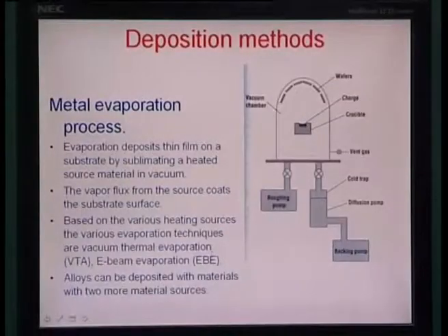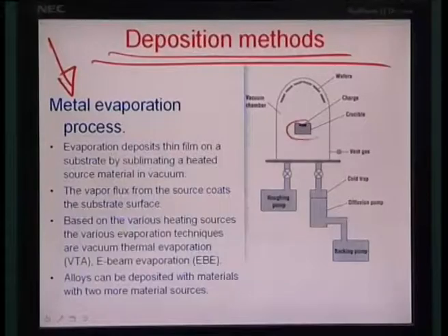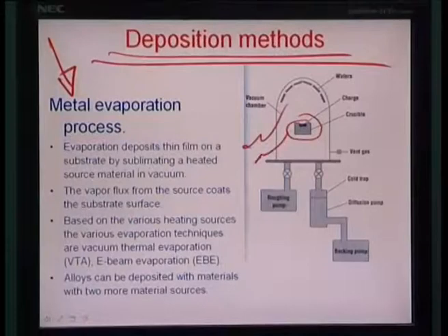Okay. So, after doing photolithography in great detail, let us look at some of the deposition methods and basically the surface micromachining methods. The first technique which comes to mind is the metal evaporation process. This is a very conventional, age-old technique where you create a crucible where you have some metal wires, like platinum wires or gold wires or titanium wires or chromium wires, and then you evacuate this chamber, sending the gases outside the chamber, and heat.